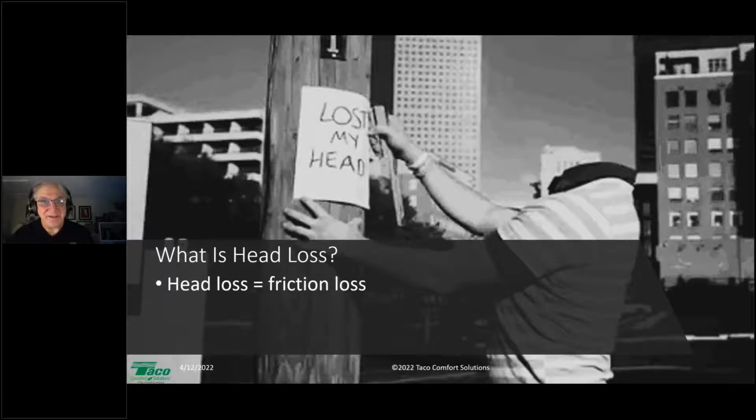Okay, so I don't have to lift the weight of the water up to the third floor. It's already filled and pressurized anyway, so I don't have to lift the water up there to get it there. But I also don't have to worry about lifting the weight of the water because coming back down the other side is the same amount of water that's acting like a counterbalance.